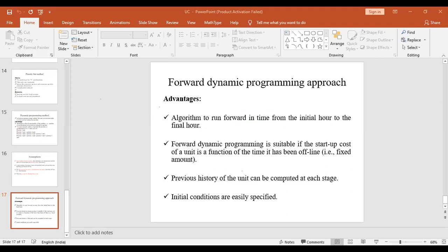For simple GATE questions which have been asked in previous years, we have to calculate the load factor for the system. First of all, the question: the total amount of power being obtained from the system is about 2000 kilowatt. If 2000 kilowatt is being derived with a power factor of 0.8 lagging for 12 hours and 1000 kilowatt at unity power factor for 12 hours, we have to calculate the load factor for the system.